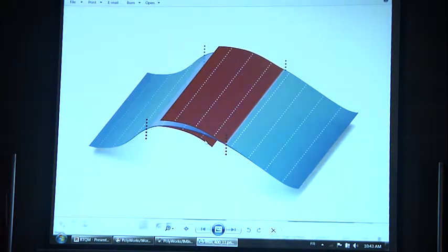And there's already a small misalignment between the scan passes. That's the same with all the devices, just because of the accuracy of the arm or the optical tracker, whatever gives you this. There's always a small misalignment between the scans. We're talking about something really small, of course. But if you want to have something really smooth, it's nice to have a single surface. So where you have overlaps, we create an average model, and we blend it smoothly with the surrounding.